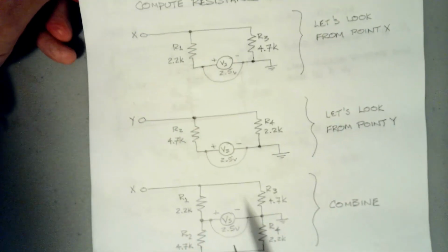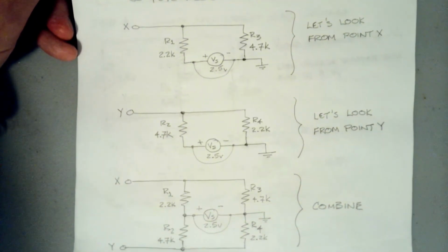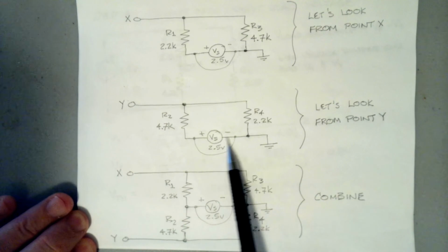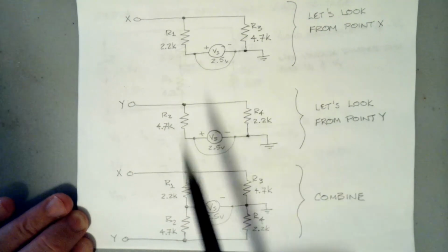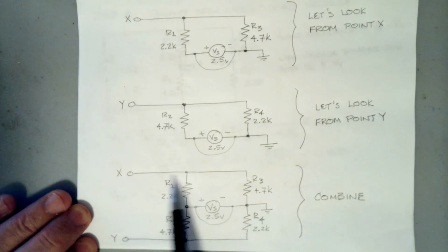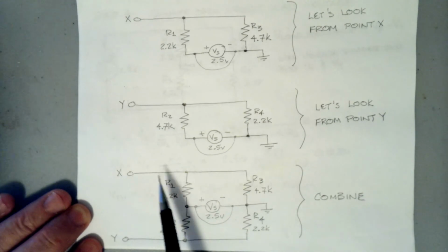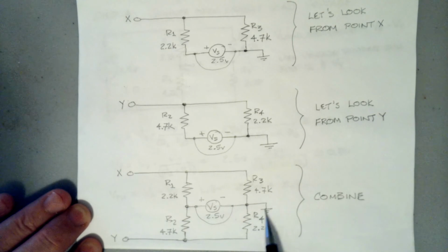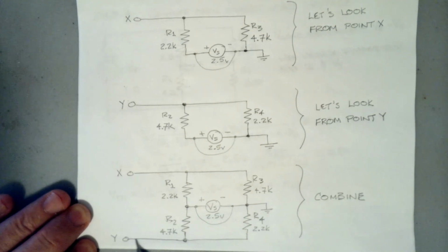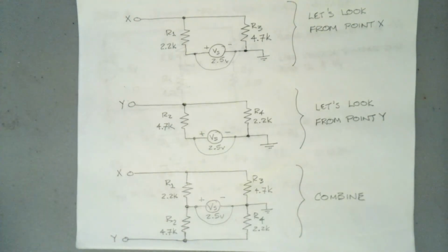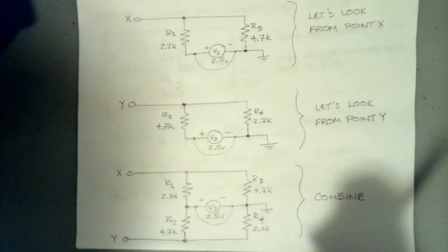And if I can get all of this in the screen here pretty much, when we put these two circuits together, of course, this shorted node and this shorted node are the same. So I got X going here, and it's going through a 2.2K to the shorted load, and it's also going through a 4.7K to the shorted load, and we can call that ground. And point Y is going with a 4.7K to the shorted load and a 2.2K to the shorted load and ground. And so we have a circuit here that's going to wind up being something we can solve. Just happens to come out that way.